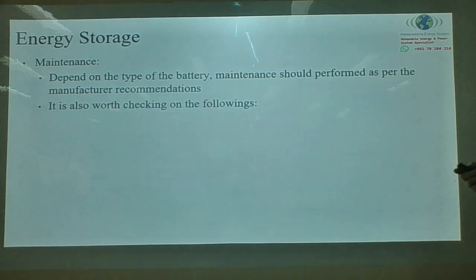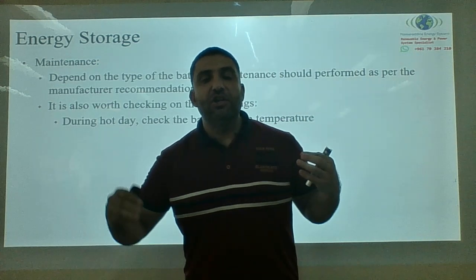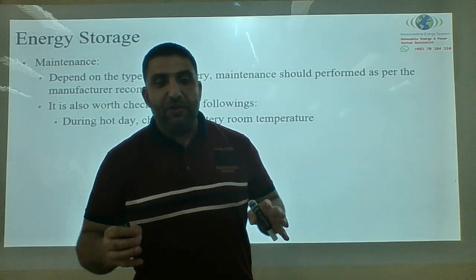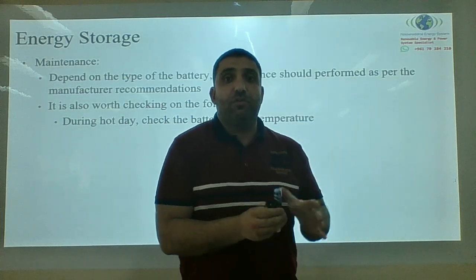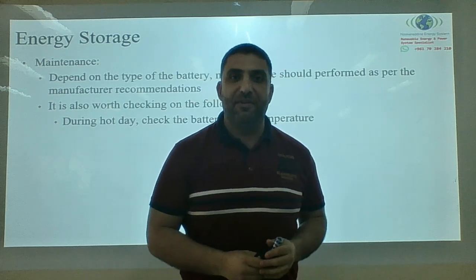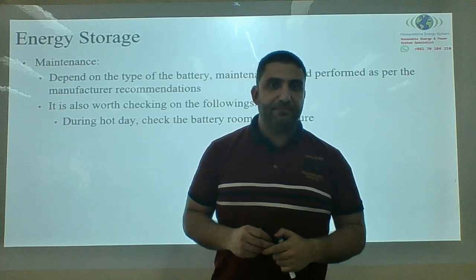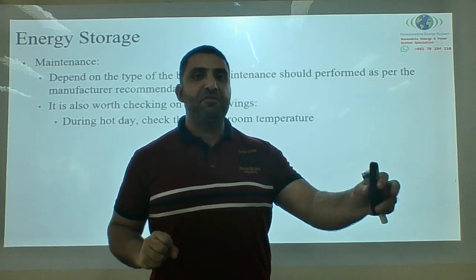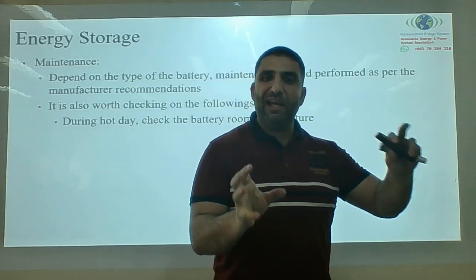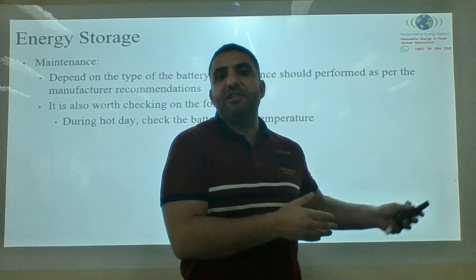It's also worth checking the following. If you have a very hot day, check your battery performance. Try to reduce the current that you draw from the battery on a hot day, unless you provide a cooling system for your batteries. Guys, if you have a car capable of taking 1,000 kilograms and you take 1,500, maybe it lasts a little bit. It can take 1,500, but it could cause damage.